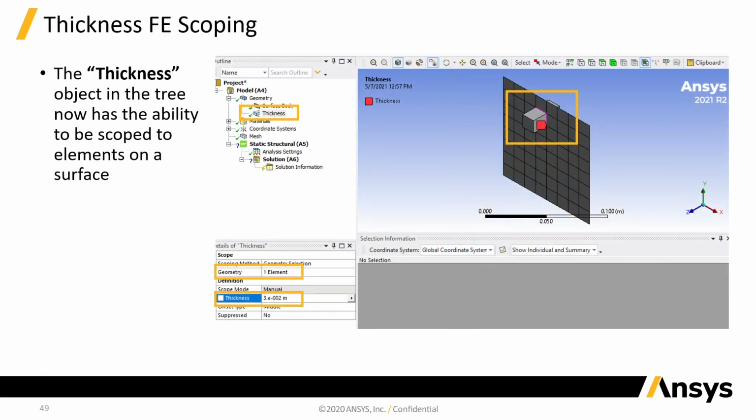Alright, if you have surface models, shell models, typically defining a thickness is done traditionally on geometric definition. So you have to basically break the model in the preprocessor, like the design model or space claim or the CAD package, and then you traditionally assign the thickness on the surfaces per surface.